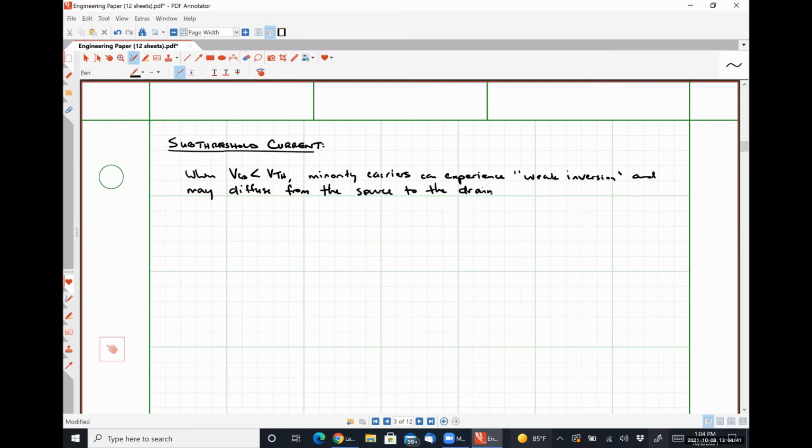so let's think about that for just a moment, okay? What does the FET stand for in MOSFET? Anybody remember? Field effect transistor, okay? So that means that it's the presence of an electric field that drives our current, right? So effectively, in a MOSFET under normal operation, everything is based on drift, right? Carrier drift. We apply an electric field which imparts a velocity on the carriers and they move. That's drift.